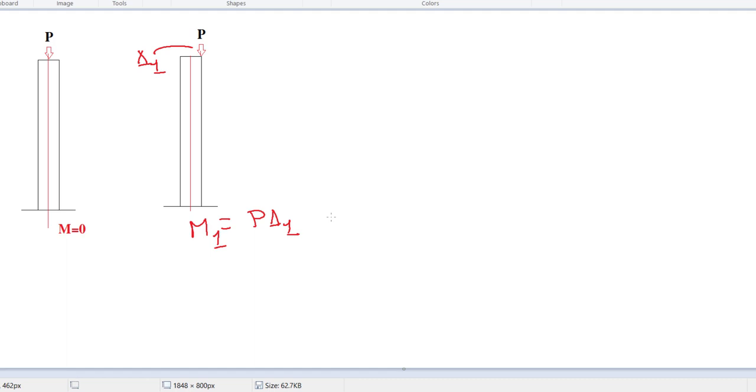Fine. So in some of the videos on YouTube or somewhere else, I have seen people explaining that the bending happens along the direction of the application of the load. But that is not true when someone was comparing between buckling and bending. This comparison was apparently very simple, like, okay, the bending is along the direction of the load and buckling is perpendicular to the direction of the load. But buckling and bending are both interrelated. Buckling is just an instability point, but it all arises from the bending.